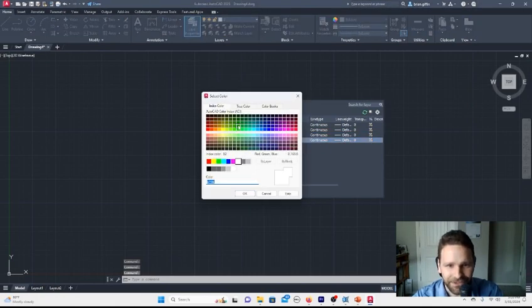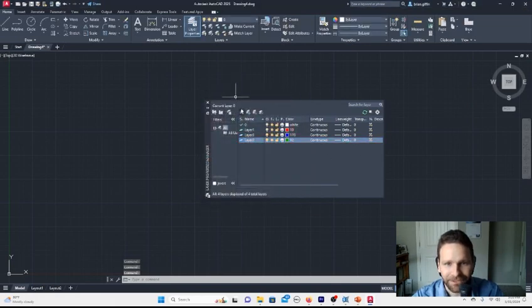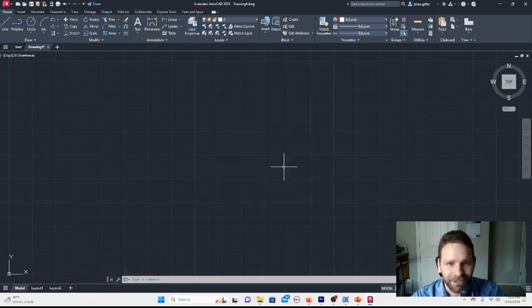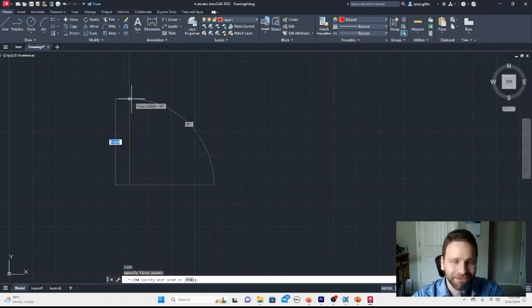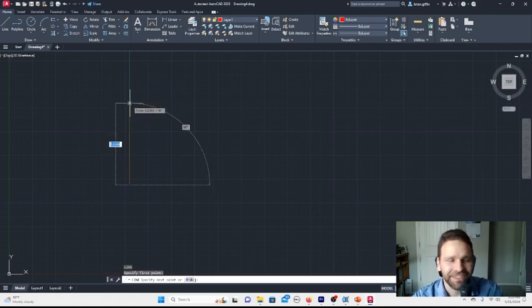The intent is to demonstrate that you can go about creating models in AutoCAD that are defined relative to multiple separate layers, and we will distinguish between members that all have the same cross-sectional properties and all of these other things based on which layer they belong to. So for example, maybe layer 1 just consists of all the structural members that will be assigned the cross-section properties for the heavy-duty members, and then maybe layer 2 will be the less heavy-duty members, but somewhere in between, and so forth.